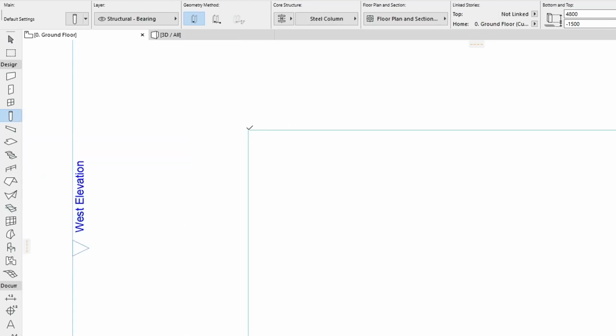Next, hover the cursor over the upper left corner of the slab and type X1500+. This way, the cursor will be moved 1,500 millimeters to the right. Type Y120+ and move it 120 millimeters higher. When done, press Enter. Let's see how we can create copies of an element to speed up the modeling workflow.